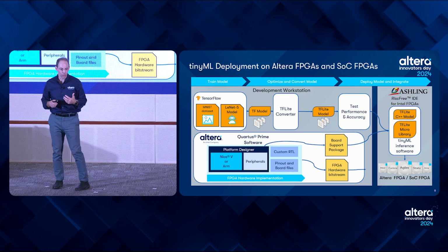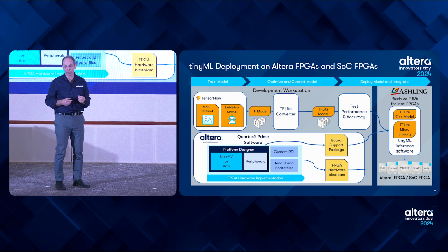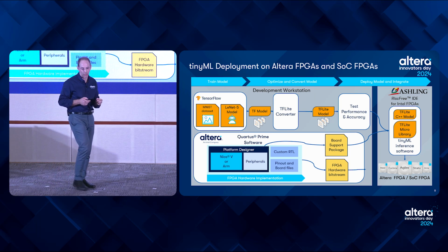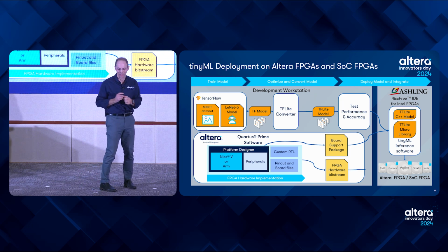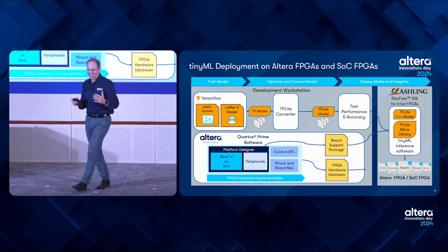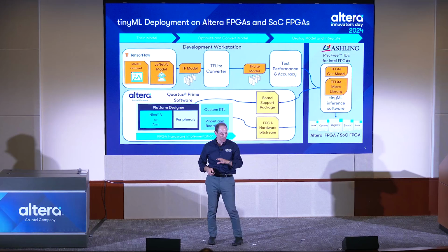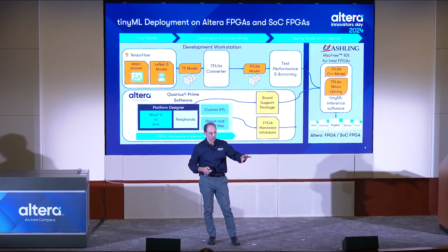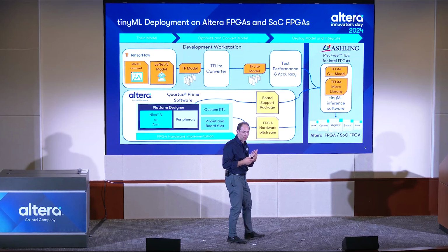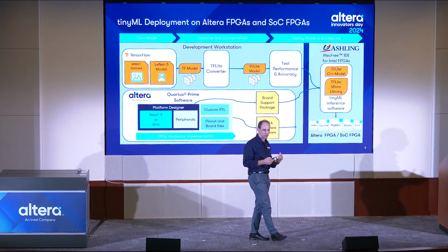We go through the process of converting that TensorFlow model into a TensorFlow Lite model. We do the testing and performance accuracy on your development workstation, but it's nothing like seeing it actually work in hardware. So the bottom row there, it's the typical development process that you have in Quartus, where you use Platform Designer to build up your system.